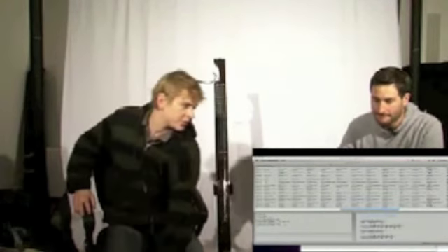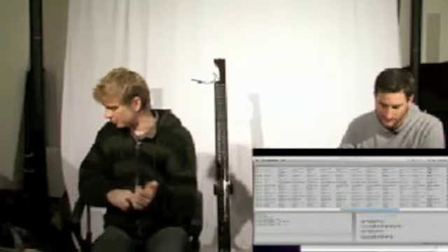Another question is, does it work on the Pico also? Yes. You're talking about the MIDI controller thing? On the Pico, there's only one MIDI out, so it's MIDI controller 1 that you're talking to. So you'd say MIDI controller 1, hey, and then obviously there's only one strip. Off the top of my head, I think continuous number 1 is strip controller, and continuous number 2 is the breath controller. So if you wanted to change the breath controller, you'd say MIDI controller 1, hey, continuous number 2 to whatever set.